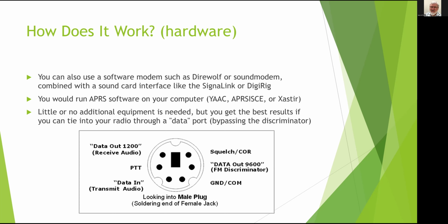The advantage of this over plugging into the keyboard and mic port on the side of the radio, or keyboard and speaker port, is typically if you have this data port, it will be pre-discriminator audio. So there's no squelch involved. You don't have to monkey with the squelch. It's always listening, and the audio is not adjusted for hopefully making voices sound better, because we're not talking about voices. We're talking about data bursts, right?